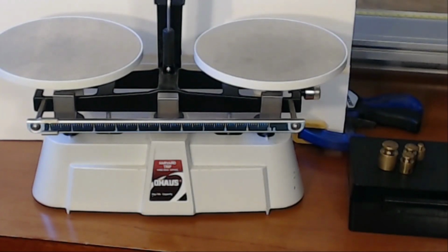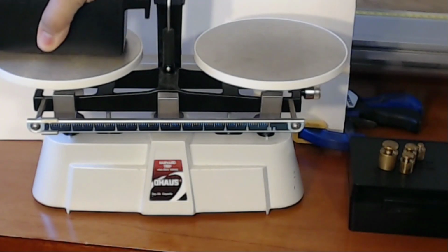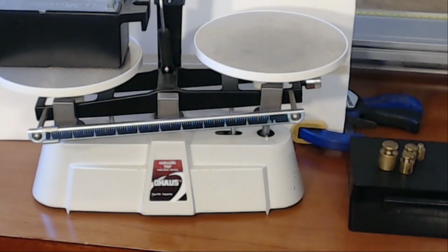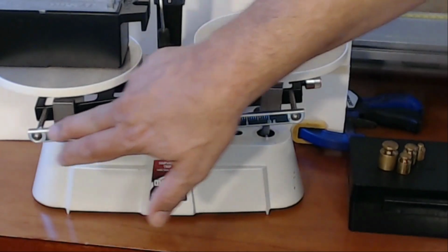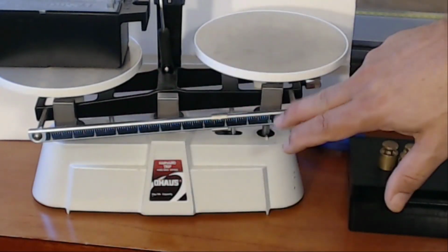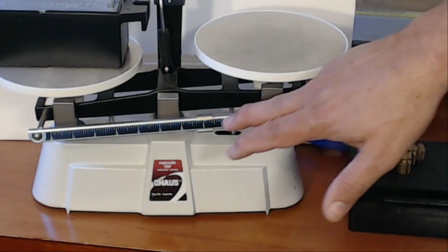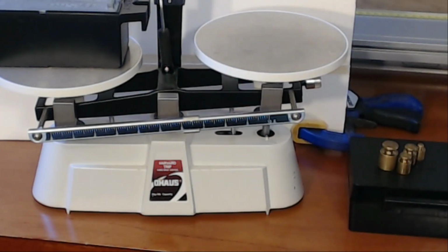We're going to put the mass we want to measure, and in this case I'm going to do the maximum, which is a little over 2 kilograms. And I'm going to put them here. The unknown mass, the part you're going to measure, always goes on the left-hand balance pan. Now we need to put masses here in order to balance this. And then we'll do the fine adjustment with this bar here. I'm going to leave it in the middle just because that's the way I like to do things.